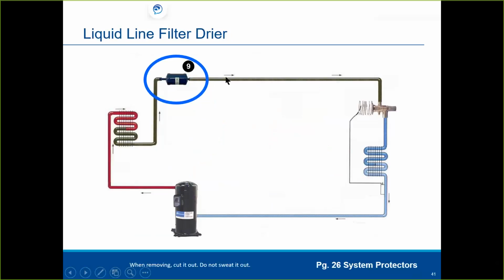Liquid line filter dryer, possibly the most important thing in the system, okay? Our best friend, if you will. When removing this, I don't want to get too far ahead of myself. When removing a liquid line filter dryer, we want to cut them out, don't braze them out.